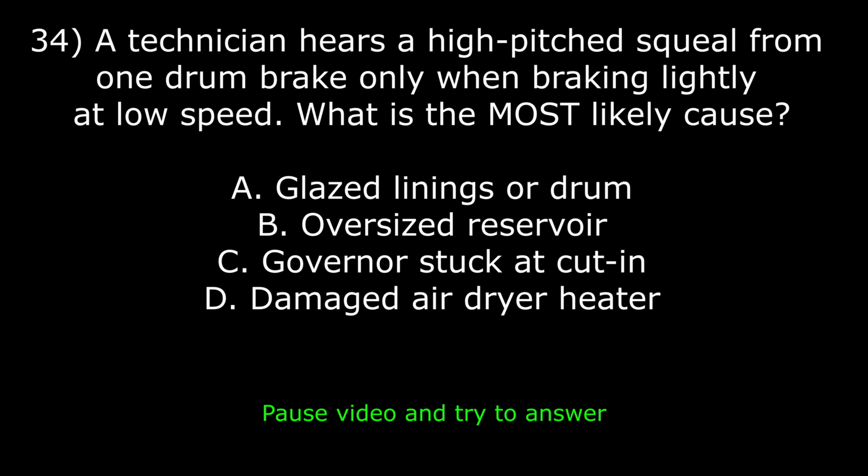35. A technician hears a high-pitched squeal from one drum brake only when braking lightly at low speed. What is the most likely cause? A. Glazed linings or drum. B. Oversized reservoir. C. Governor stuck at cut-in. D. Damaged air dryer heater. Correct answer is A. Glazed linings or drum. Explanation: glazing can cause squeal, especially at light applications.